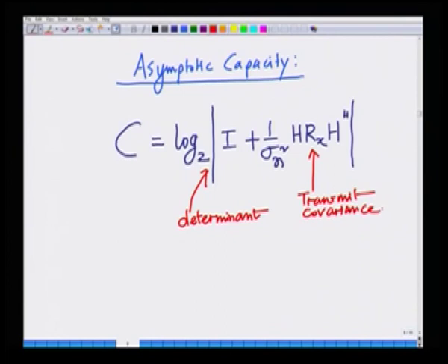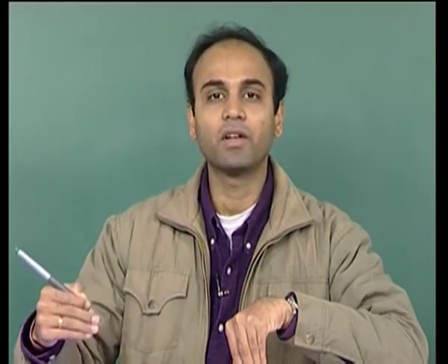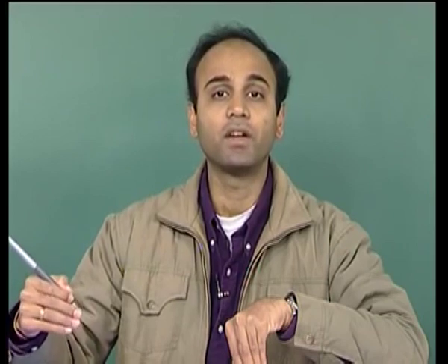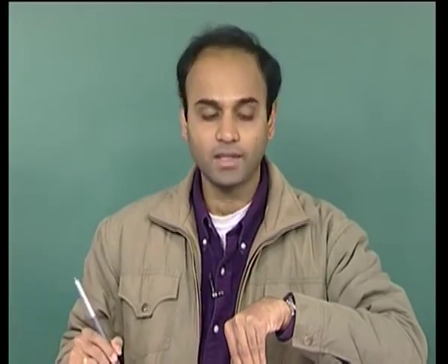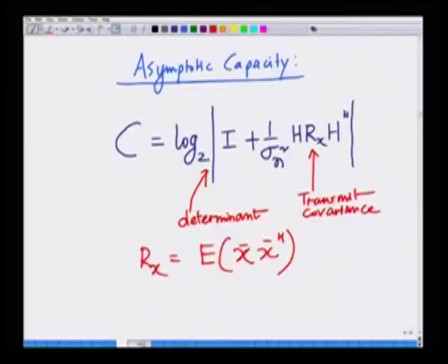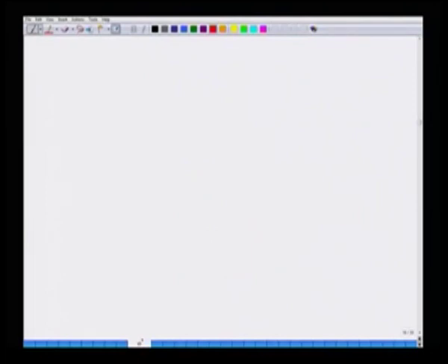That is, it shows the power profile of the transmitter symbols. In fact, R x equals expected x x Hermitian. This is the transmit profile. What this shows is what are the powers allocated to the different transmit symbols from the different antennas. Already you might remember it, we have considered the transmit covariance even in the case where we derived the MMSE estimator. Okay.